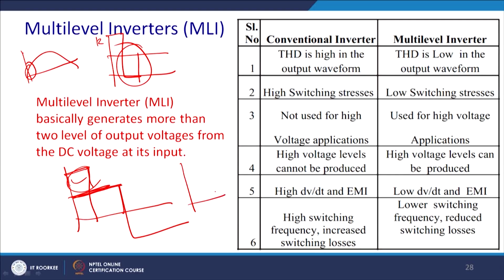But assume that you have steps, you can apply 6 volt as well as 12 volt. So, once we want to generate 5 volt, you can turn on only 6 volt. So, there is less instantaneous error between the applied voltage and the actual voltage required, and thus the unnecessary harmonic generation will be lower, and this is the basic essence of going for the multi-level inverter.